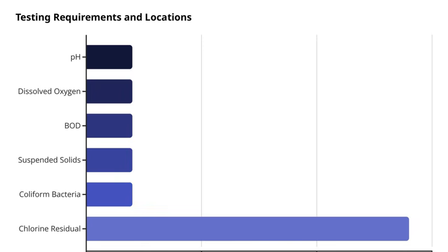Now, let's talk about interpreting the water color. A deep green, sparkling color usually indicates that the pH is high and the dissolved oxygen levels are satisfactory. That's a good sign that the water quality is healthy. On the other hand, if you notice dull green or a lack of color, it suggests that the pH might be declining and dissolved oxygen could be lowered, which can stress aquatic life. Gray coloration is a sign that the system might be overloaded or that there's improper operation happening. Recognizing these color cues helps us quickly assess the water's condition and take appropriate action. This ties into the overall goal of maintaining healthy, balanced water systems.